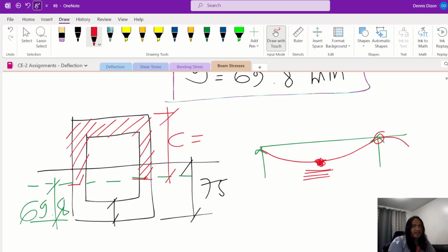And then near the support, if it is a rigid connection, of course, you only see a simply supported beam in the case of a bridge, like a girder, where you have the pin connection at one end and the roller connection at the other end. But in a regular building, unless you are using precast, then for sure, the conventional framing, which is beam and column with rigid connection, has negative bending at the support. That's why at the very support,